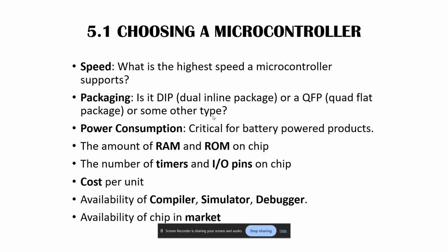Now it depends on whether you need a DIP, a quad flat package, an SMD package or any other package. It depends on you. Like the SMD in the Arduino Uno, where an SMD microprocessor is used, while in DIP a DIP microprocessor is used.